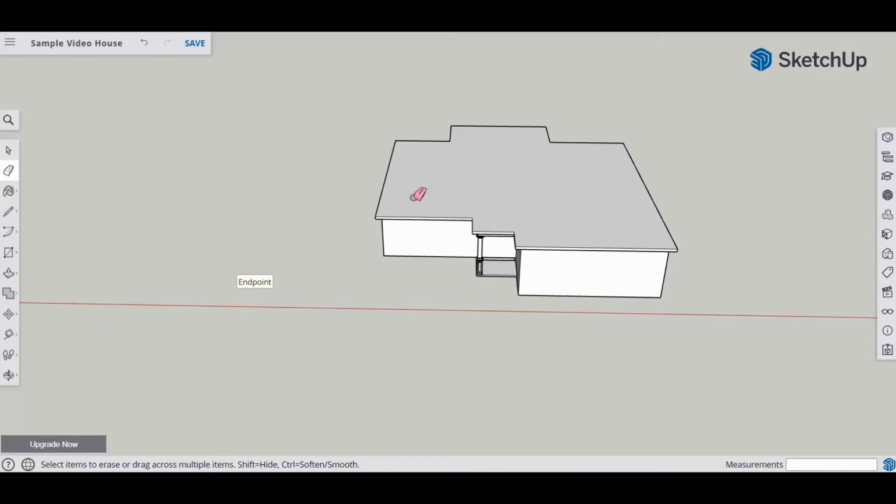Now what we have to do is to put our gable roof on. Now there's the main gable roof that goes across this house this way, and then there's a gable that's back here and the 2 gables up front. Because the gable runs this way, that's the main gable roof, and so any gable that goes 90 degrees to it is going to be considered a reverse gable. So that's a reverse, reverse, and a reverse. So let's put our main gable on first.